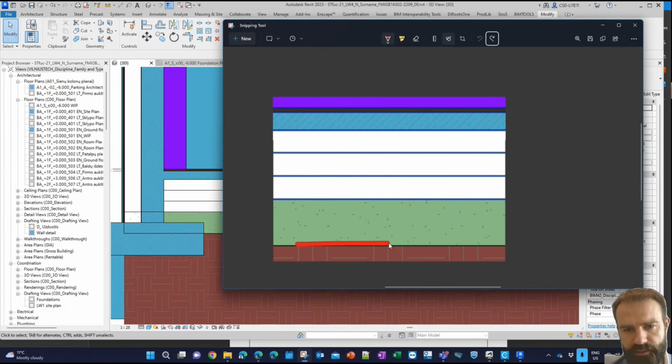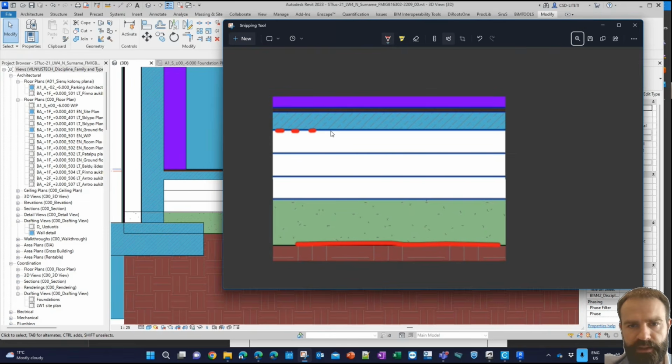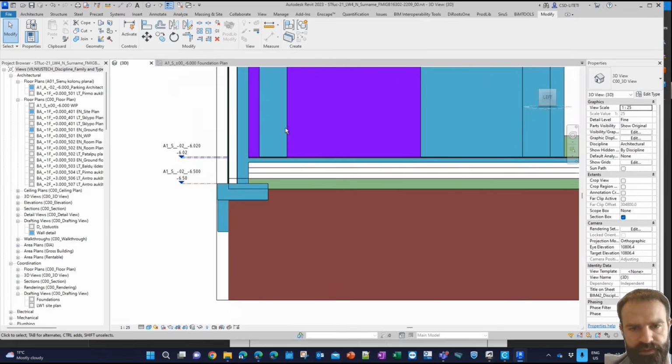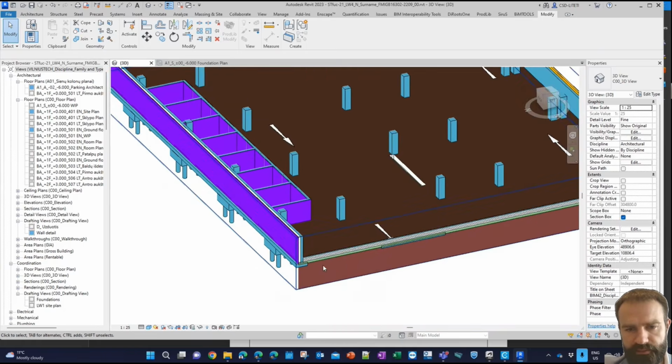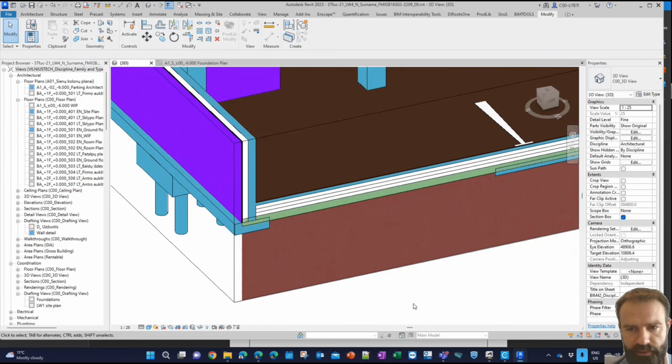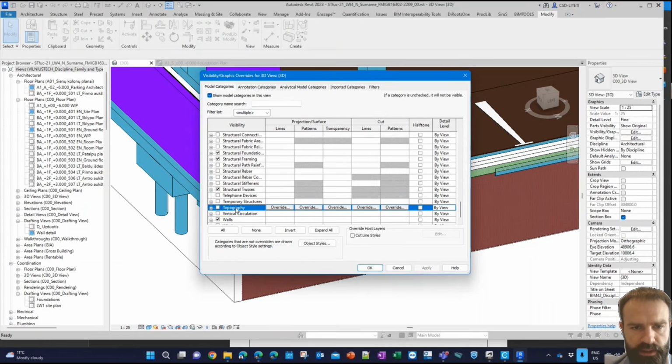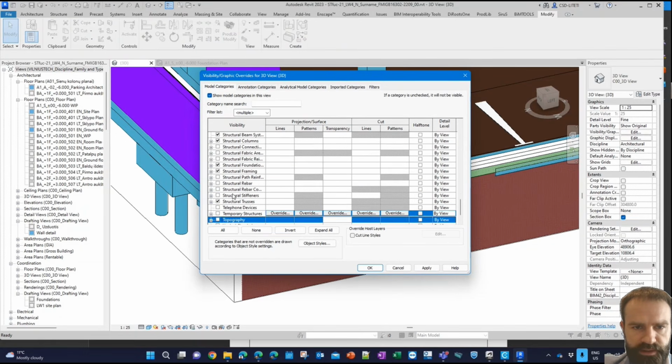Of course I need to put a geotextile here, and my membrane layer is located here. Later I can use a dashed line to represent this membrane layer for my drawings. From a 3D model perspective, this is the correct use of all these layers. And now I will turn off topography and site, so I don't need it.